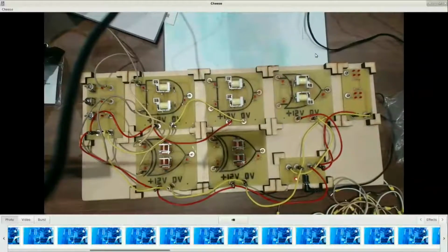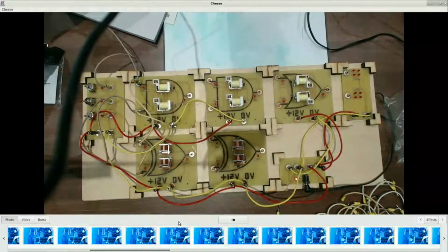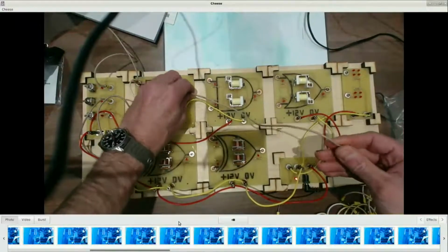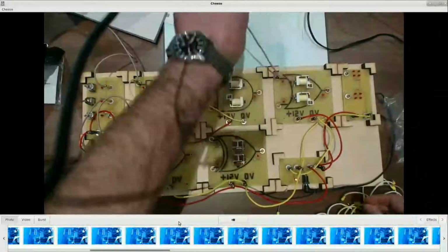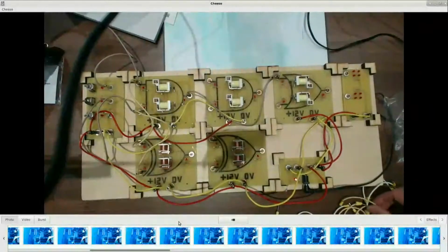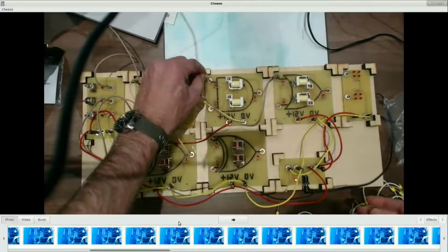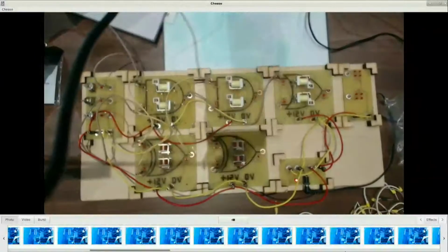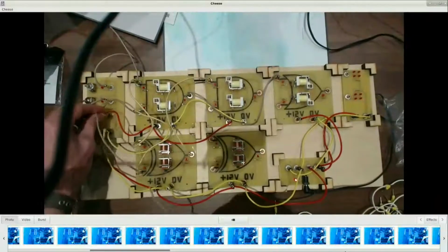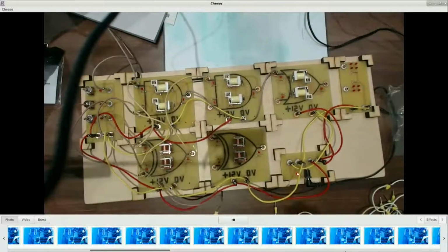So the output of my AND gate goes to my OR gate. So here we go, we're connecting to my OR gate. The output of my exclusive OR goes to an AND gate. So I've got another AND gate at the top there. My carry in from the previous stage also comes into that AND gate. So there's carry in coming up to that one there. So my second half adder is along there.